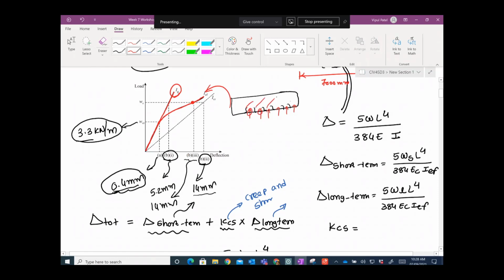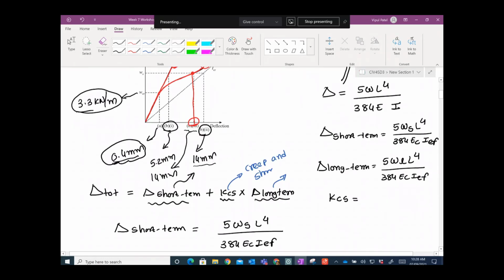Of course, in the crack it will not carry any tension load, but the concrete between the cracks will have some effect, so therefore you have some resistance. So therefore the standard says you take I effective. For that case we use these deflections, right? So that is the short-term deflection that we take into account.